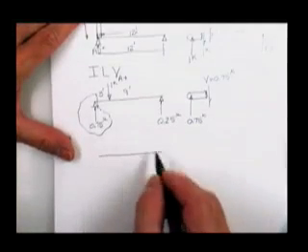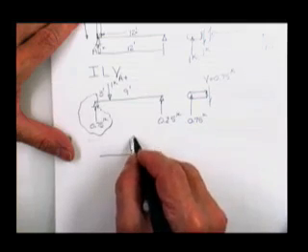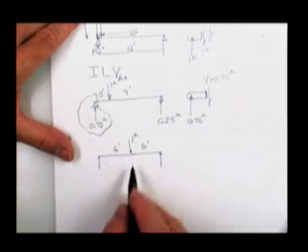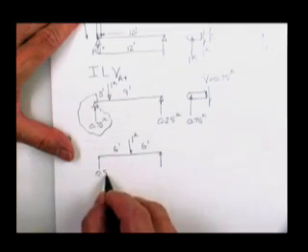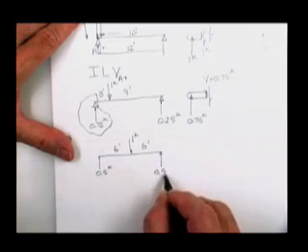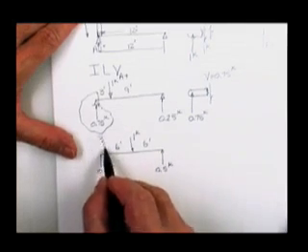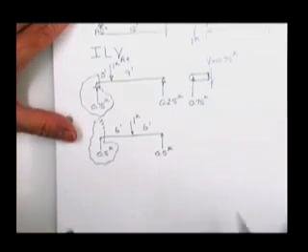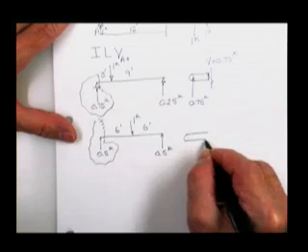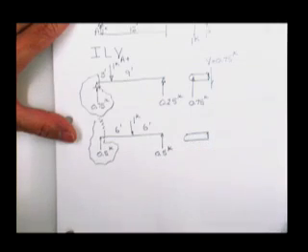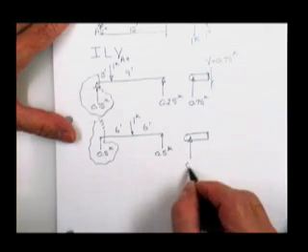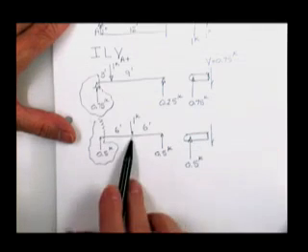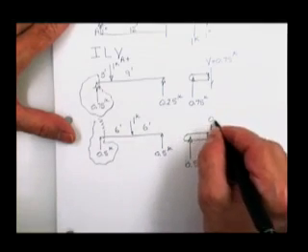Number 3, when you put the load in the middle, I know I'm going to get a half a kip here and a half a kip here. And I want to know the influence on the shear slightly to the right of that point. Here's your free body. The length of that little piece right there is 0. Here's the 0.5 reaction on the left end. Here is the shear caused by the 1 kip load at this position, 0.5.